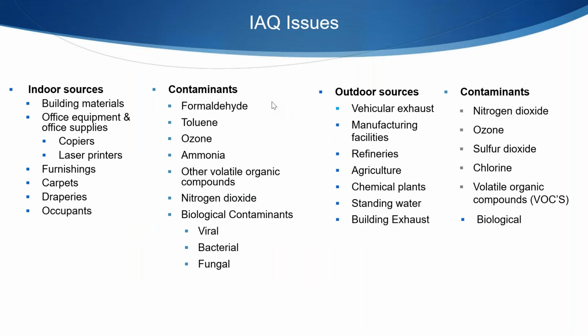So, other indoor air quality issues. I'm not going to do you the disservice of reading off a slide word for word. I apologize for that, but I leave this in just to point out that biological contaminants can come from different places. Now we're talking about from people, but keep in mind things that people have traditionally used UV for: bacterial contamination on coils, mold contamination on coils. Those have all been things we've used UV on in the past. But a pipe breaks and there's standing water. These are other ways that biological contaminants come into the building besides right at the coil.